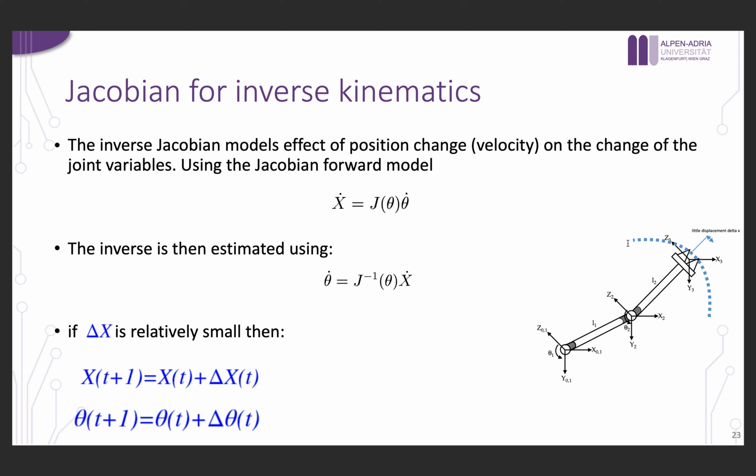For example, I have this path, okay? This path, of course, represents the change of the movement. So I want to move this robot arm along this path with a specific velocity. And this velocity is represented by that, so this is known. This we can get by the inverse of the matrix, and then we can get the change of theta. Now, as I said, if we can get the change of theta, we can know the change of x(t) because it represents that.